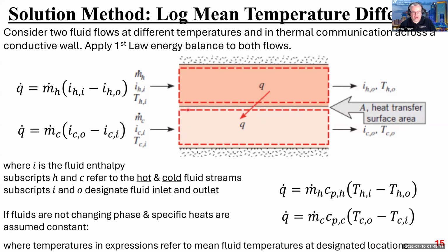So it's actually potentially colder on the edges than it is in the center or vice versa. And these temperatures do not account for that kind of pipe scale temperature gradient. These are just average temperatures across the entire diameter of each one of these pipes. So just be aware of that as the derivations continue to advance.